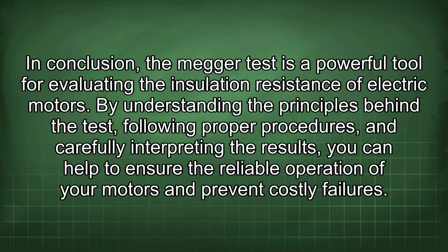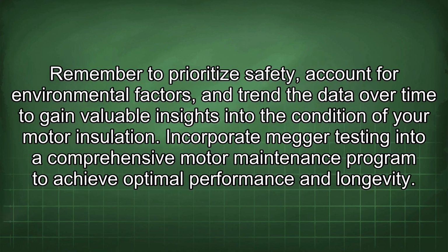By understanding the principles behind the test, following proper procedures, and carefully interpreting the results, you can help to ensure the reliable operation of your motors and prevent costly failures. Remember to prioritize safety, account for environmental factors, and trend the data over time to gain valuable insights into the condition of your motor insulation. Incorporate Megger testing into a comprehensive motor maintenance program to achieve optimal performance and longevity.